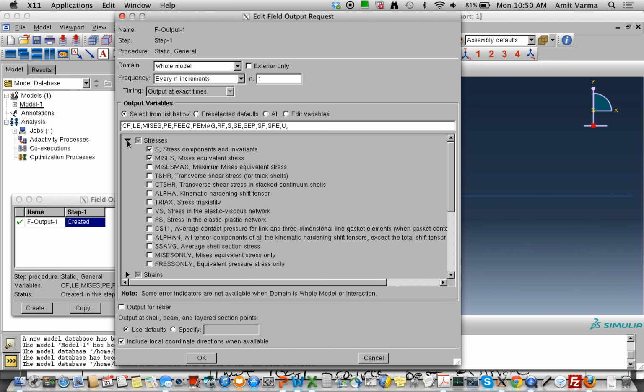After which you get to interaction. There's nothing really for us to do here. We get to the loading and look at the boundary conditions. We've specified fixed end boundary conditions. Now, if I remember this right, you have to do a problem that has an axial force. Is that right? Yeah. If you have to do a problem with an axial force and you completely restrain both ends, you can't really apply an axial force, right? So you have to make sure that at least one of those ends, the end where you're applying the axial force, is free to undergo axial translation. You understand what I'm saying?